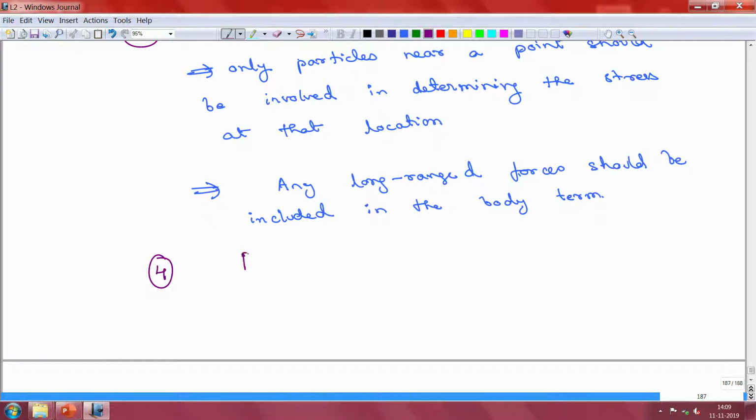And then finally, there is the principle of determinism. The principle of determinism is the belief that the current state of stress is influenced by history, but not by future. So, when we say there is memory, that means that in the integral it is okay to integrate from minus infinity to t, but not beyond any point given the current time. Right.